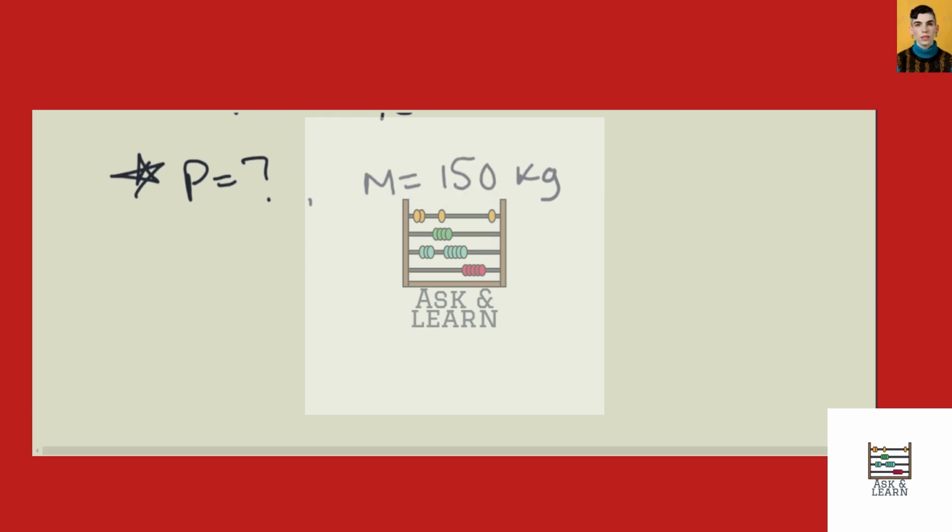So we know that the height of each little step is 125 millimeters. If we divide by 1,000, we get 0.125 meters. We're also given the length of each little step, which is 250 millimeters. And if we divide that one by 1,000, we get 0.250 meters.